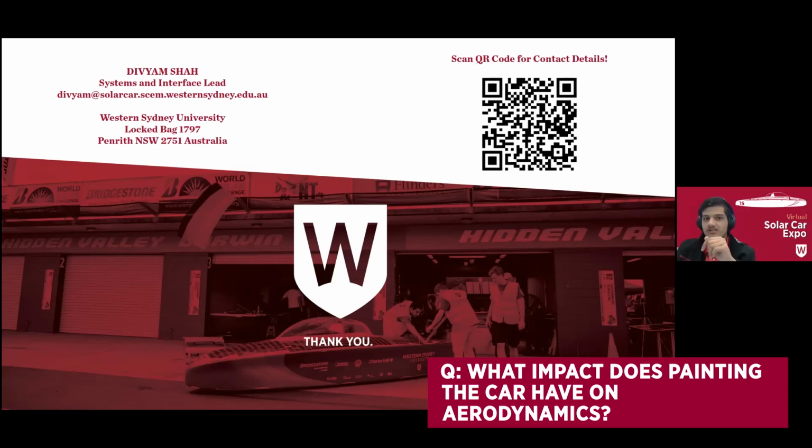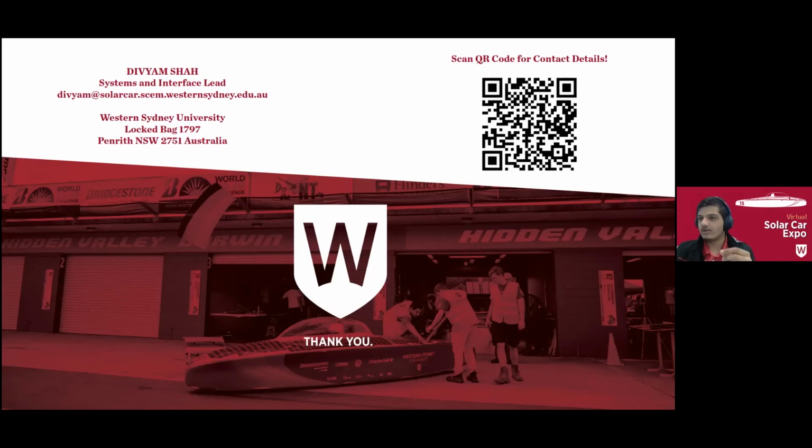No, absolutely. That's a great question. So there are a few types of drag that affect a body moving through the air, but one of them is the skin friction caused by air shearing across the surface, and that is a relatively large contributor to the overall aerodynamic drag of a solar car. And so having a smooth surface finish is very important. But more important than that, honestly, is having smooth transitions between different parts of the car.